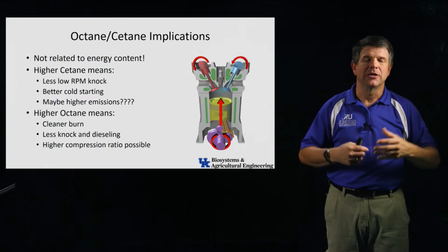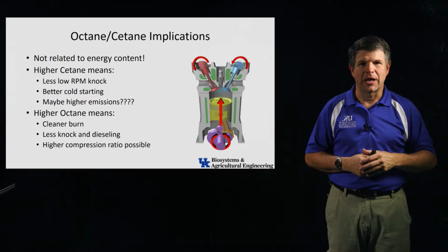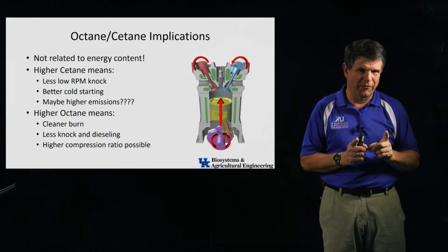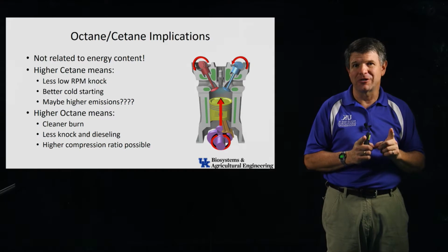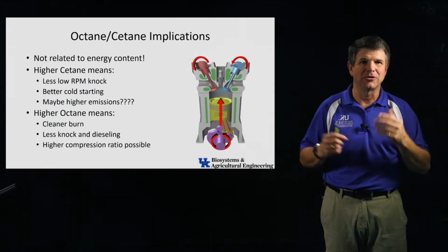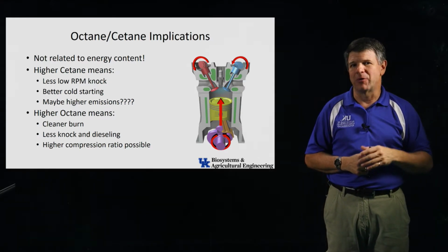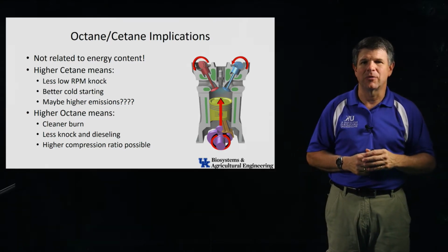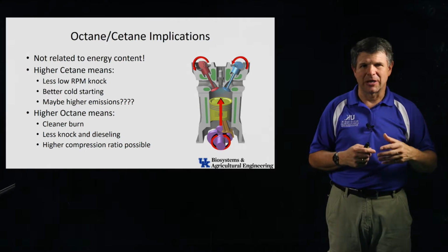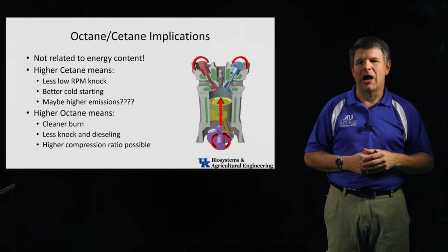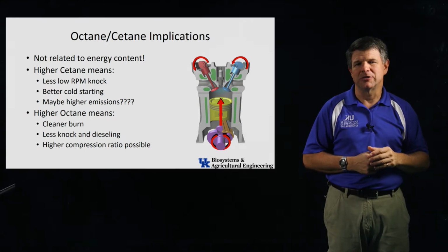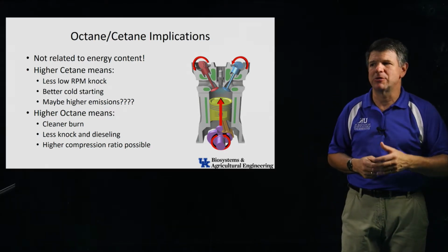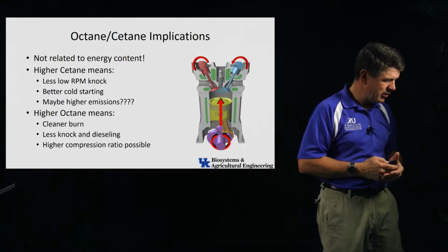Higher pressures get more performance out of those engines. Okay, we're building up a lot of heat, so you'll see those blowers on short performance type things. So drag racers, where they run a quarter mile and shut them off and that's it. Tractor pulls and stuff like that, same thing. NASCAR, where it's got to be more of an endurance, you won't see those blowers, so they're going to run just a higher compression ratio in the engine to be able to keep track of that. All right, so they've got to watch temperatures, got to watch pressures, and so forth to keep all that going.